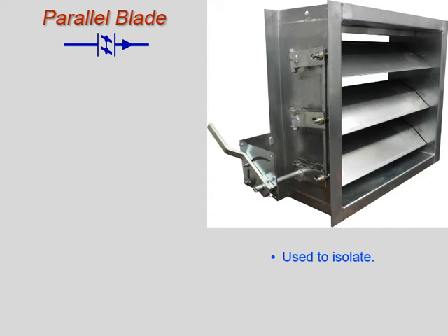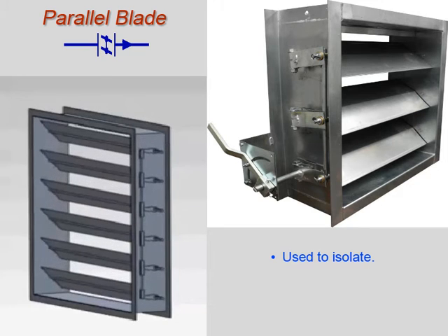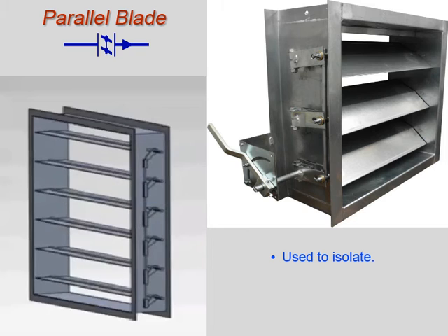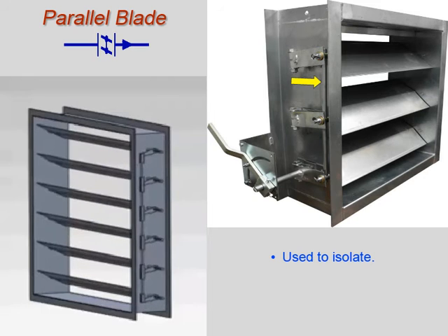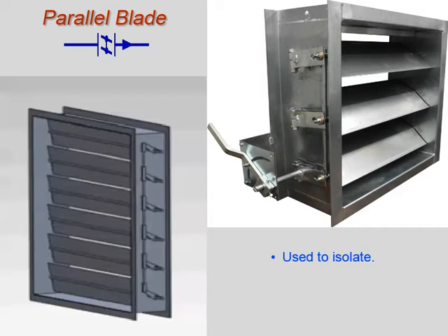The blades may have vinyl or silicone rubber sealing strips on the edges to provide a tight seal when the damper is shut. The blades are connected together by a linkage assembly which moves all the blades as a unit. A galvanized steel actuating rod connected to the blades moves them all together. The actuating rod is connected to a pneumatic or electric actuator.